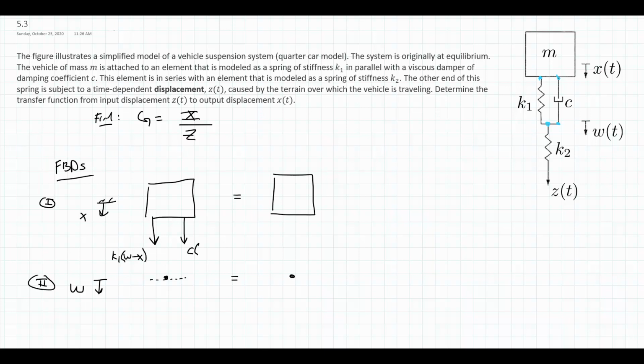So here, a W dot that is positive if we hold X dot at 0, so the top of the damper is not moving, but W dot is. W dot positive causes it to stretch, causing tension. So W dot positive, and then we'll have a minus X dot.